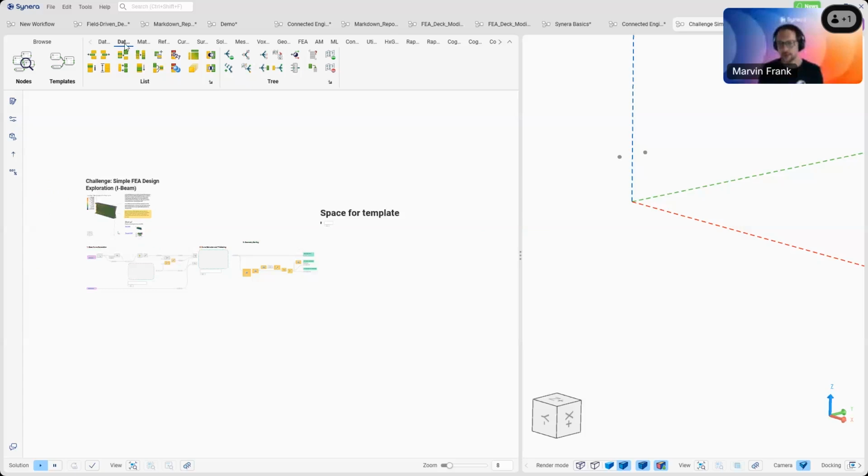For example, this is a very simplified example of a car door. Just assume you have a design space, and in that design space we want to stiffen this surface with CAD stiffening ribs based on shell models, so surface-based design. At first, we have a simple FEA of that door, so everything here is fixed. You can see that in these little triangles, and then a simple force is applied here in the middle.